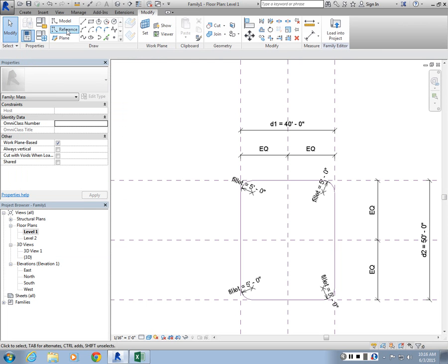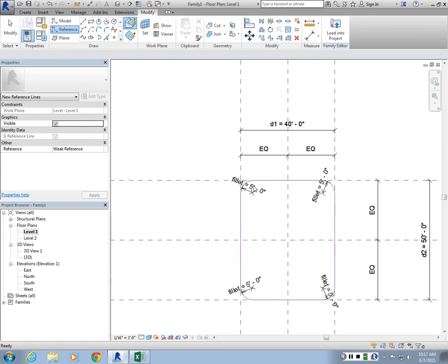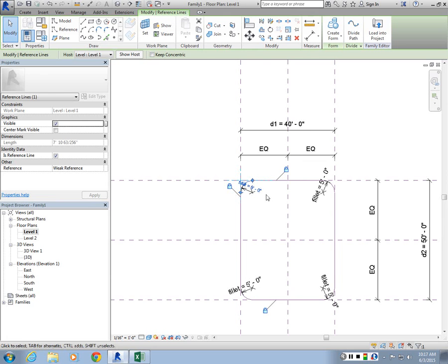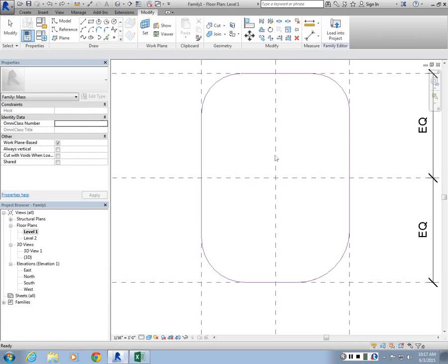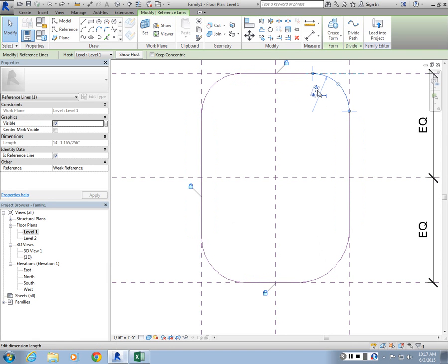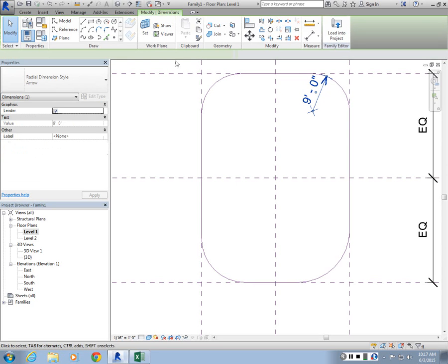The fillet, go to reference, choose fillet arc. You could also do fixed radius after you choose 2 lines, or you can manually enter 1, then activate the dimension. You want me to do it again? Choose the corner fillet, then it will highlight the dimension for its radius. Click on the dimension and enable it. So I'll do it again. So I had all of them done. Then you come in here, choose the arc, activate the radius dimension, and then you can choose this and define it as a parameter. Right?